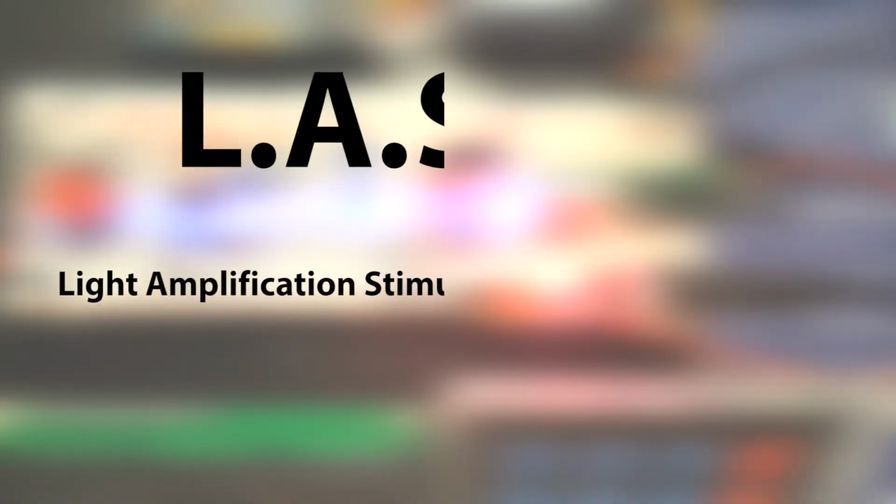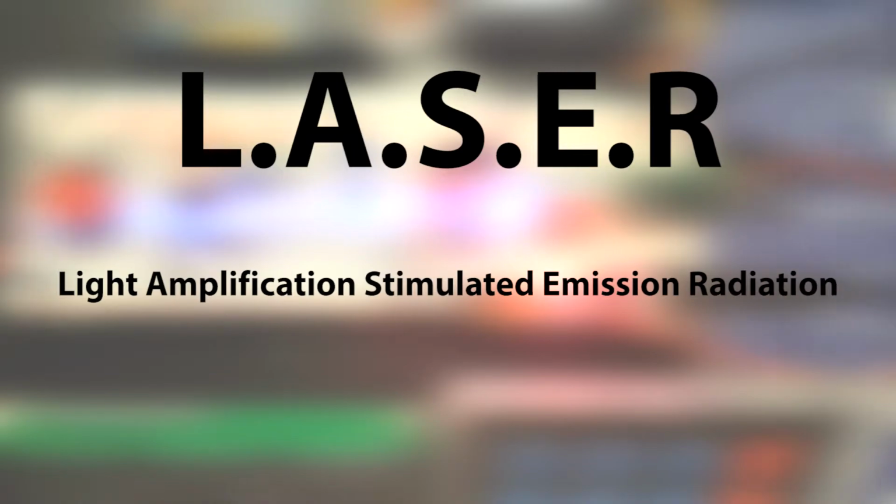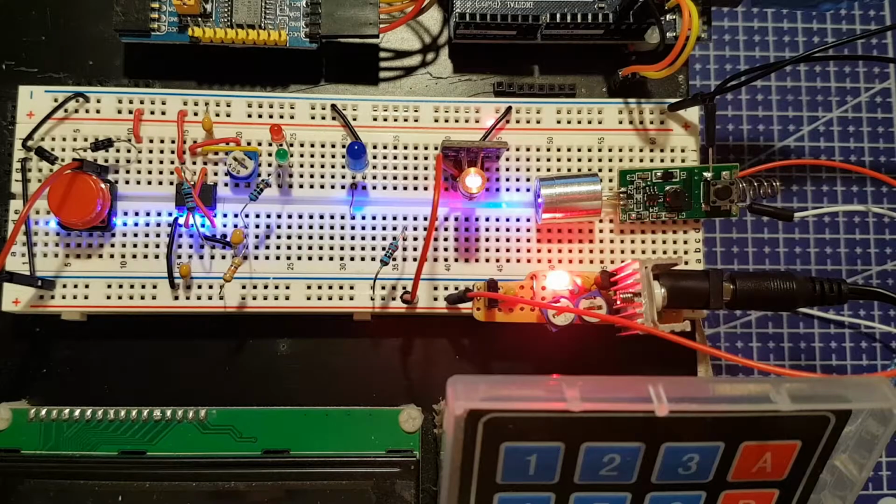Last on the list we have the laser diode, or light amplification by stimulated emission of radiation. Like the LED, a laser diode emits light, but it's monochromatic and coherent, so it's one specific colour wavelength and all of the photons of light are parallel and moving in the same direction. Just a warning, if you're planning on playing around with a laser, they are very dangerous and can cause blindness even from reflections off dull surfaces. Also, they can cause burns and fires, so please be careful and always wear eye protection. You can get laser glasses for the specific laser wavelength you are using.